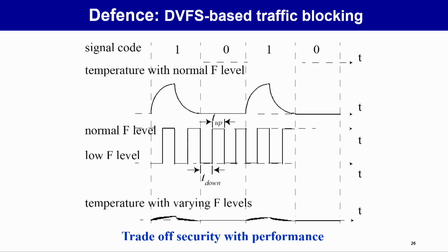So this frequency that we are changing is like the power input to the core. Typically in processors we change only the frequency. This is matched to a power level. There are like 20 or 30 frequency levels. You change from one to another, and it goes from one power level to another power level. So this is one defense, changing simply the frequencies. All right.